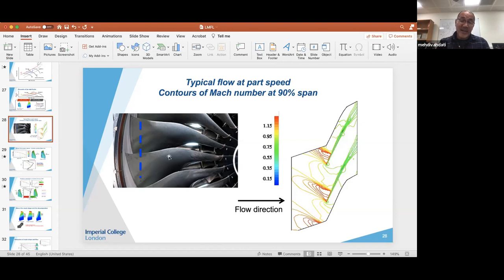And the other thing that I didn't mention at all is the leakage flow. I ignored it through this presentation, because the flow coming from the pressure side to the suction side would influence the flow on the upper part of the blade, which consequently can feed into the flutter part.